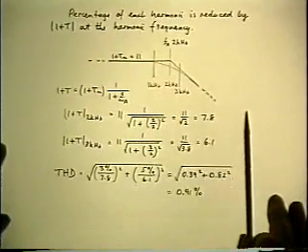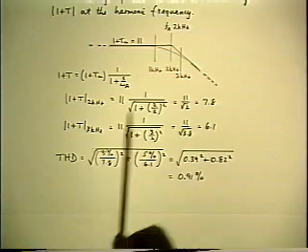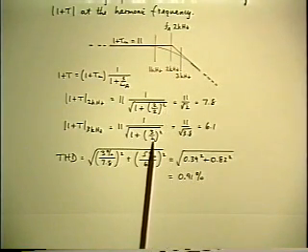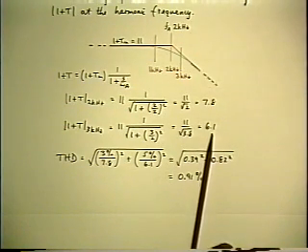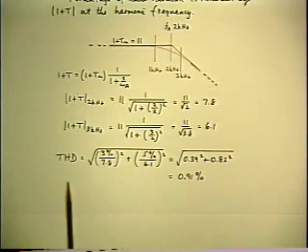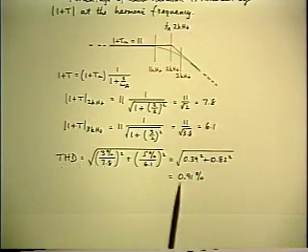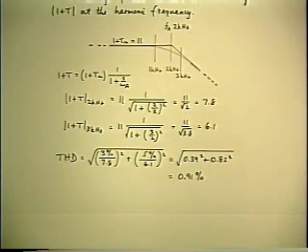Then you do the same for the third harmonic. Evaluate the magnitude of F at 3 kilohertz, so that's 1 over the root 1 plus (3 over 2) squared, which comes to 6.1. So that's the reduction factor for the third harmonic. And then the definition of total harmonic distortion, THD, is the RMS combination of all of the harmonics that are present.